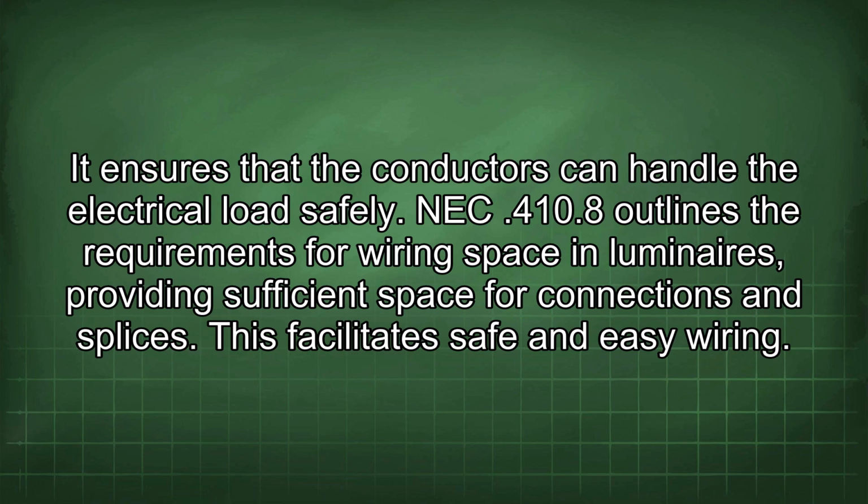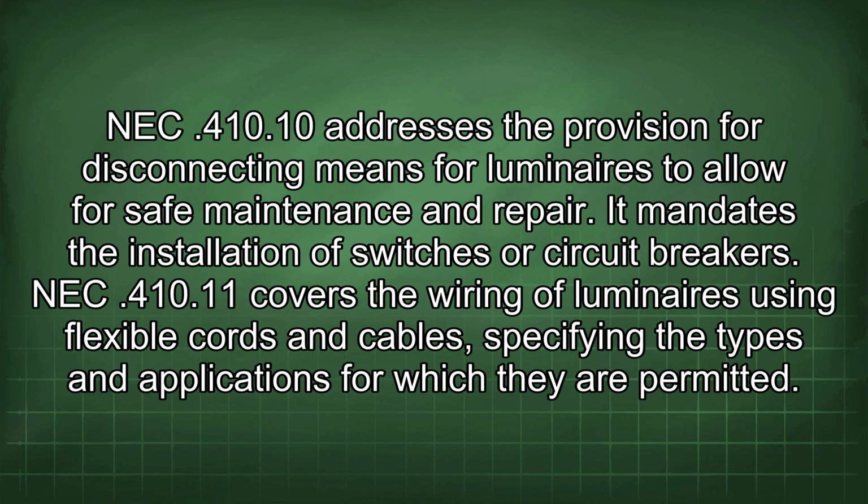NEC 410.8 outlines the requirements for wiring space in luminaires, providing sufficient space for connections and splices. This facilitates safe and easy wiring. NEC 410.10 addresses the provision for disconnecting means for luminaires to allow for safe maintenance and repair. It mandates the installation of switches or circuit breakers.